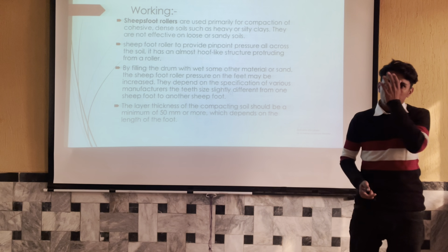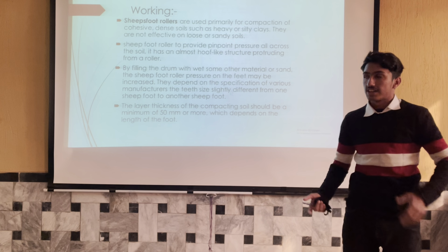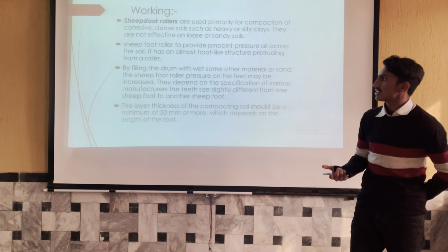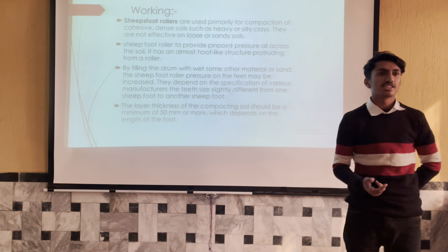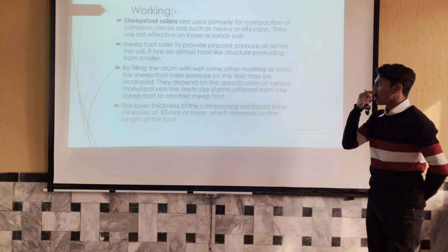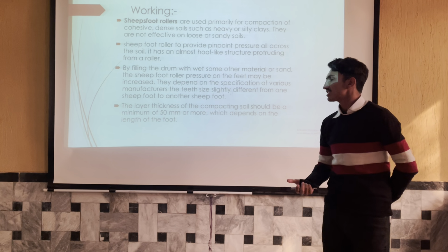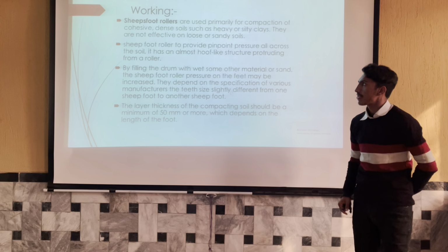As already told, we can increase the drum weight by adding some filling material like sand. Because of that, we can get a minimum layer thickness of 50 mm, but that is the limit, it should not be less than that.